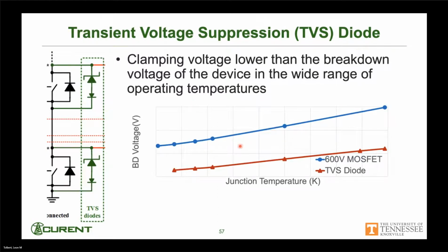So basically, you look at what is the breakdown voltage rating of your device over a junction temperature range, and you add these diodes and make sure their rating is a little bit less than whatever this rating is. If this is 600, maybe use something like 500, just to make sure you don't get close. So it's just some additional protection that you could add if you're concerned.